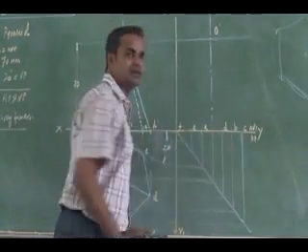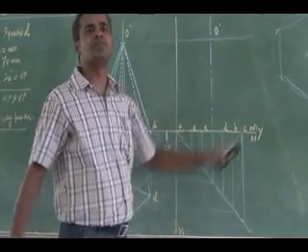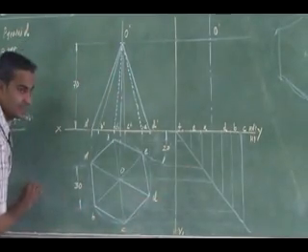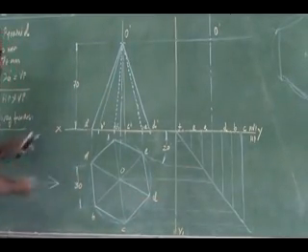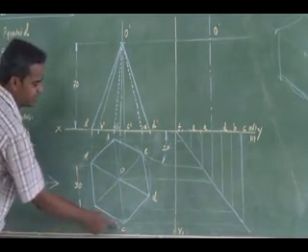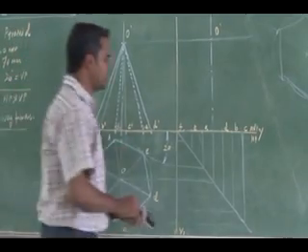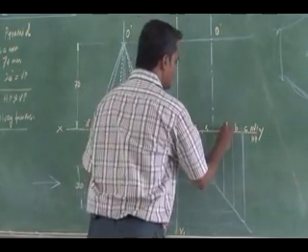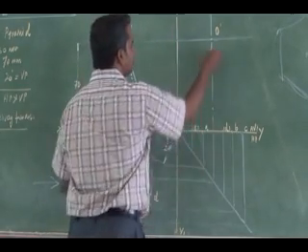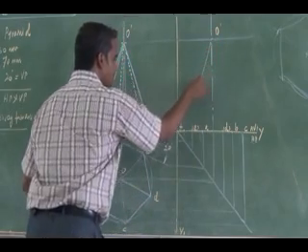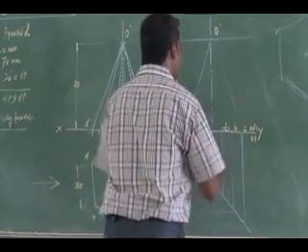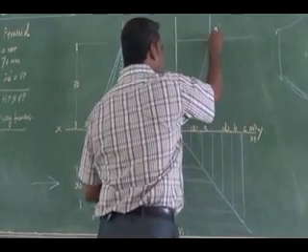Right? So once you have marked this, then you draw the side view. Okay, left side view. Which one is visible? If you look at this side, this is going to be my left side. By looking from this left side, I can see F, A, B, C. I cannot see D and E. So D and E are hidden from the left side. The other slant edges will be visible, so I can join the other slant edges as visible lines.